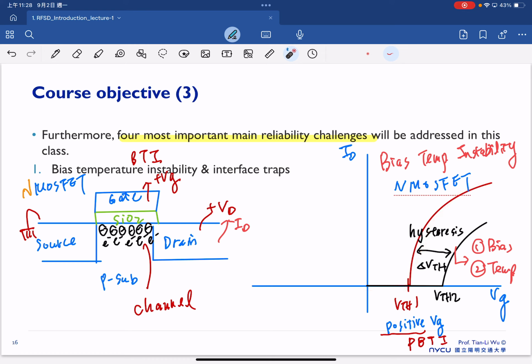But on the other hand, we also have the case we call the P MOSFET. But here we won't draw the P MOSFET again. In the future, we will have some explanation later. But the P MOSFET has a completely opposite direction of the IV compared to N MOSFET. So it's also very simple. First, you apply the negative gate bias. With enough negative bias, you start to have the current here.